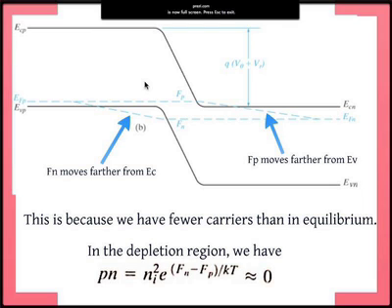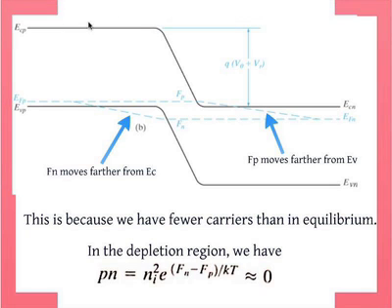Now, if you look at the band diagram, it's the opposite of what we saw before. So first of all, we are familiar with this now, that the energy bands are bent more. Okay, you've increased the energy barrier under reverse bias. That's the conduction band, valence band. If you look at the quasi-Fermi levels, the behavior is the opposite of what we saw before, and it can be explained by what we see in the carrier extraction. So far away, of course, it's still the equilibrium. Nothing's changed. As you get closer to the junction, they split.